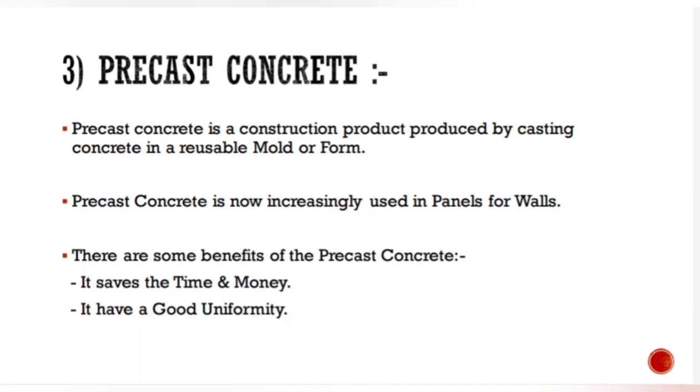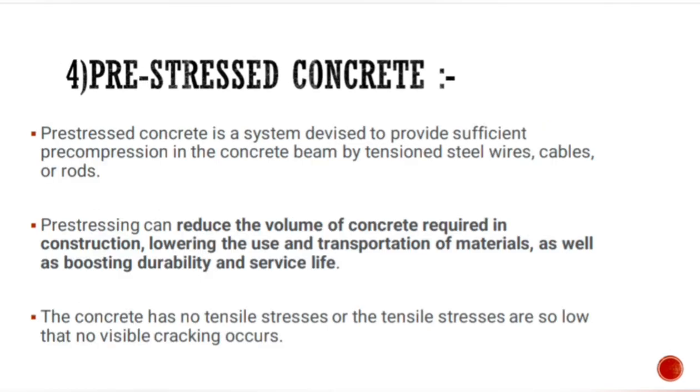Third, precast concrete. Precast concrete is a construction product produced by casting concrete in a reusable mold or form. It has many advantages. It saves money and time in the construction work. Fourth, pre-stressed concrete. The method of providing pre-compression in concrete is known as the pre-stress method. Pre-stressing reduces the volume of concrete required in the construction.